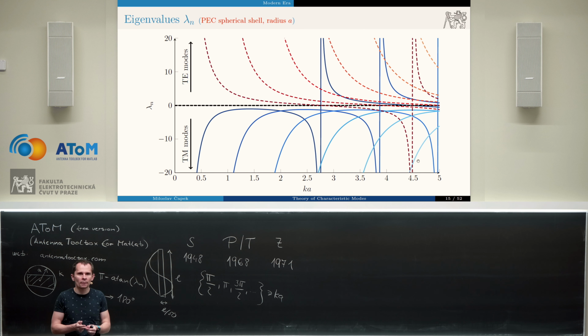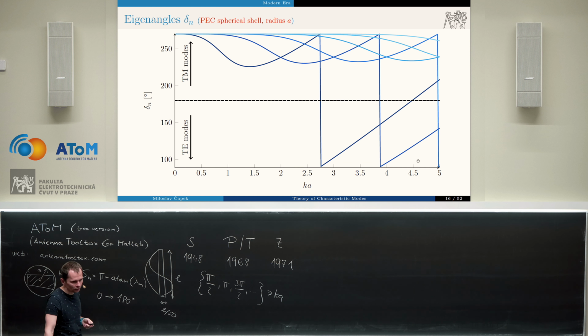And finally, the smooth spherical shell is typically not well conforming with the discretization we use, because in our case, we typically employ a triangular discretization. So this gives you a nice, or more or less nice, spherical shell only for an extremely high number of unknowns and triangles. So this is a pretty challenging example after all for your validation.